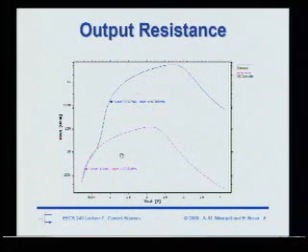That's not really a fair comparison because now we're getting a gigaohm. But still, the drop happens because one device goes into triode and then the second device goes into triode. In the region where both devices are in triode, the output impedance is roughly the same.